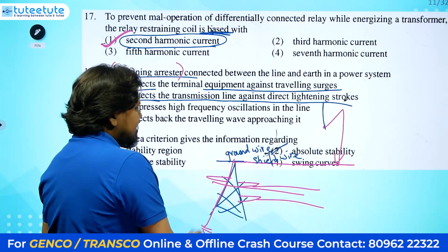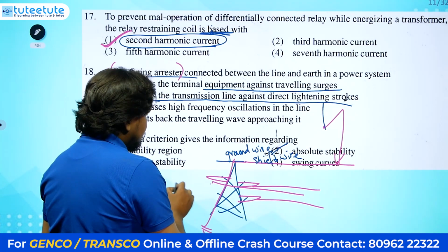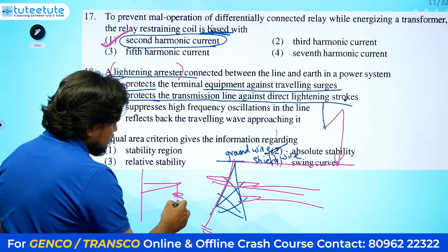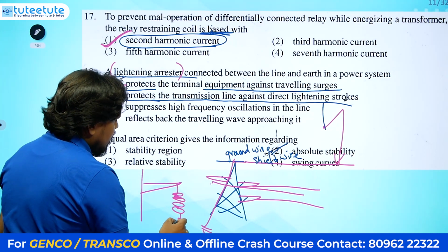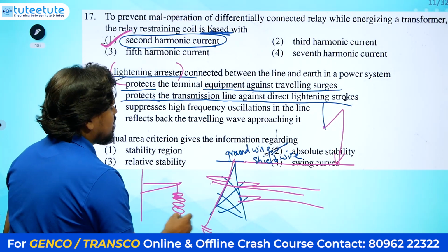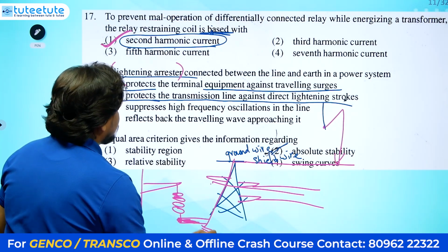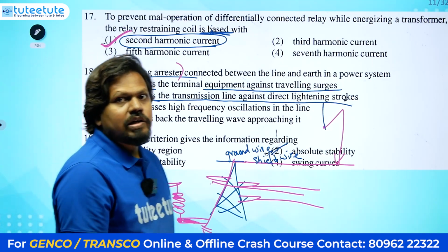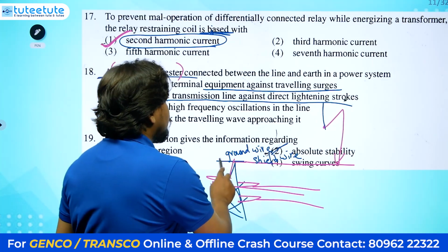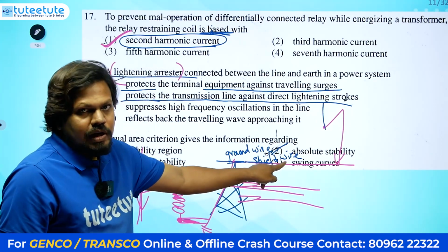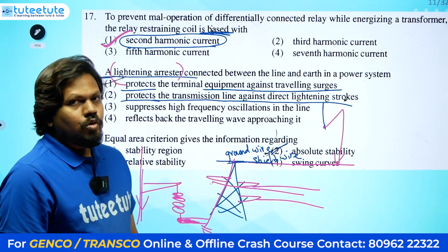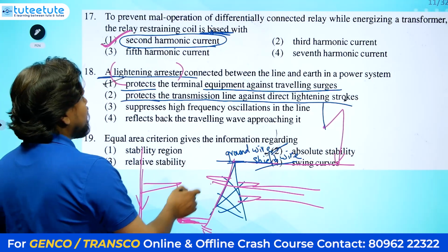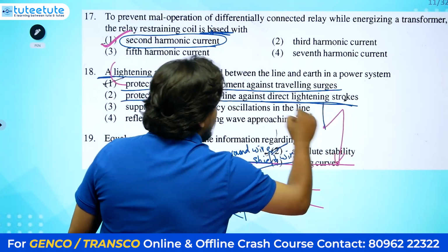But that is not connected to our power lines, because there are certain insulators, like these suspension type insulators. After that only the conductor is present, so the current will go like this only and will not enter the power lines. That is the idea, and that's why we have given this. Anyway, in a different question we will understand more points about this guard wire, otherwise shield wire, which is given for direct lightning strokes on the transmission system.